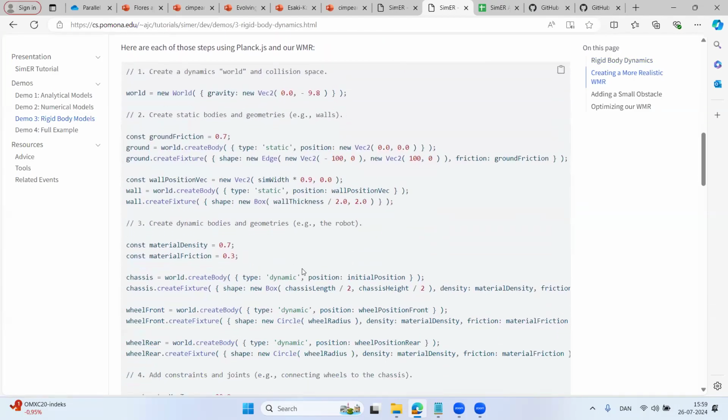You'll see pretty much the same format for any rigid body dynamics engine that you use. They all start with essentially creating the world. And here I'm creating the world with gravity of negative 9.8 meters per second squared. Be careful to look at the actual documentation for units. For the most part, you can think of a physics engine as entirely unitless, and as long as you're consistent in what you're giving it, it'll work just fine.